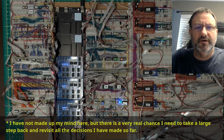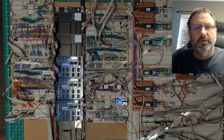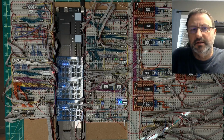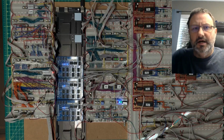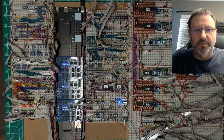In other words, I've got 12 inverters in there that is delaying a clock signal to the point where I'm trying to get a spike out of the clock so that I can do some things in kind of an intermediate state. And the faster that I run this clock, the less time I'm going to have for that state to settle before the next clock cycle or the next clock event takes place.